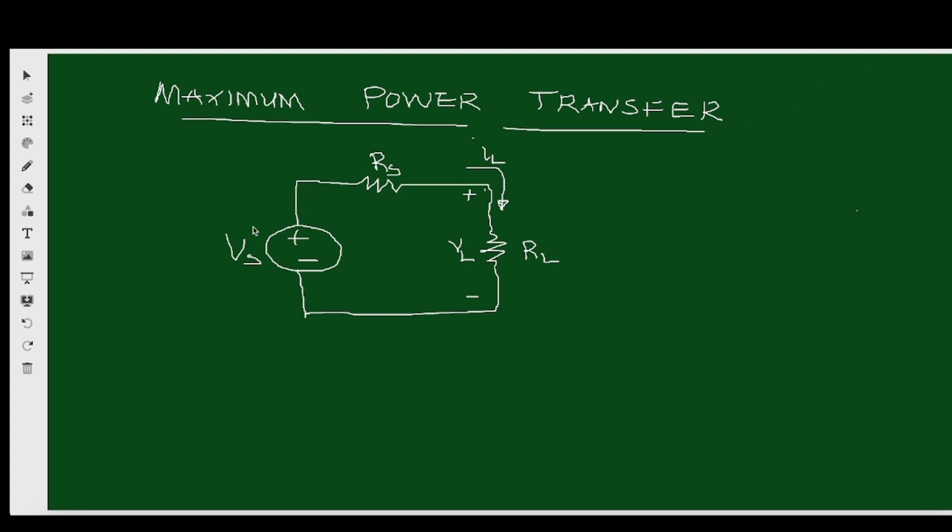So this is a voltage source, right? The voltage source, for a practical one, that is the one you see physically, has an internal resistance, and that's what we usually call the Thevenin equivalent resistance. So this is a practical source, and a load resistor is connected to it. We want to see the maximum power transferred to the load resistor.